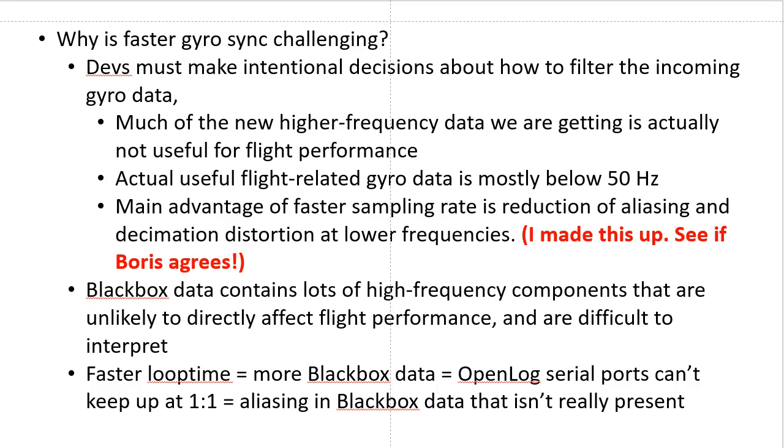So when you're sampling at 500 hertz, your Nyquist frequency is 250 hertz, and whatever's going on above that is, I mean, it just is what it is. You can't do anything with it. You can try and maybe pre-filter the data. You know, there's things you can try to do, but at the end of the day, you just got to kind of accept it and deal with it.